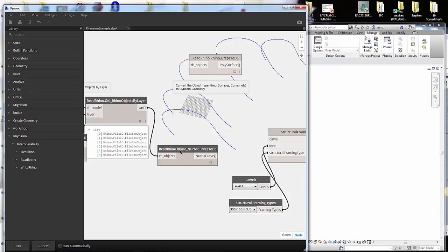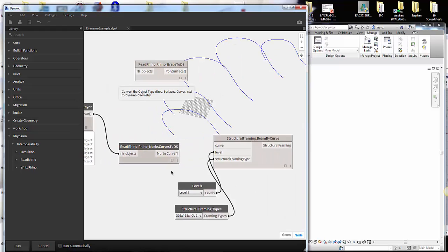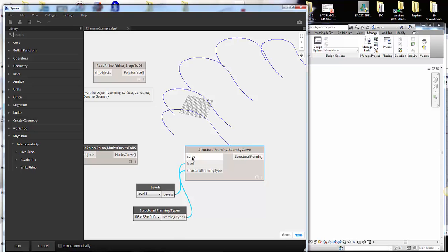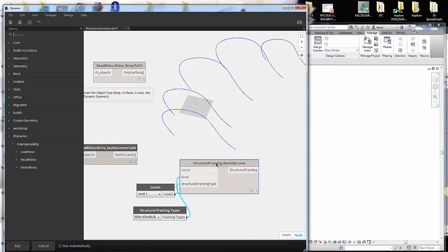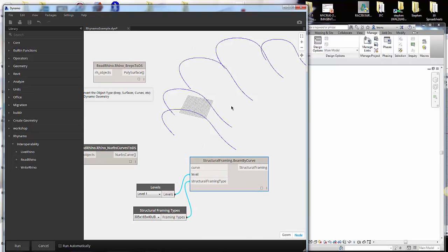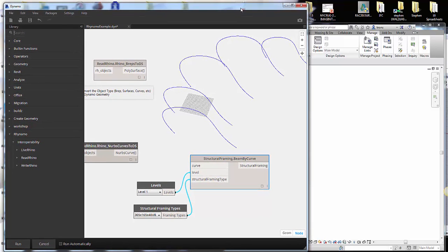If you're running this automatically, the moment I save my Rhino file, it's just going to update in here, which is pretty magical. But running automatically can start to create some overhead, especially when you get into creating Revit geometry, which is the next part of this, and also where it becomes pretty lovely in terms of interoperability with Revit. So Dynamo right now is essentially being a pass-through. It's allowing you to clean up your Rhino files to make them appropriate things for Revit to consume. It also means that you can get some relatively lightweight geometry going on over here without the overhead of imports.